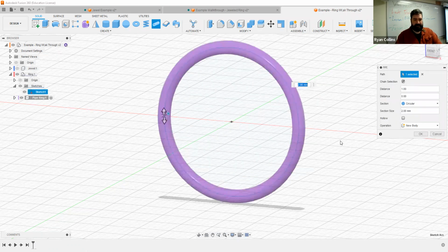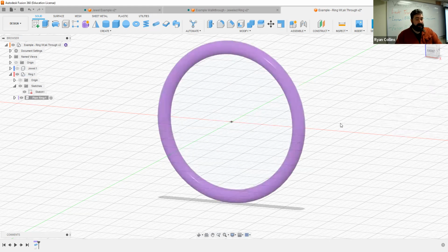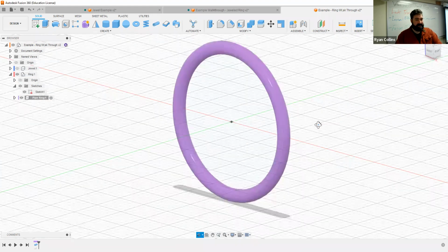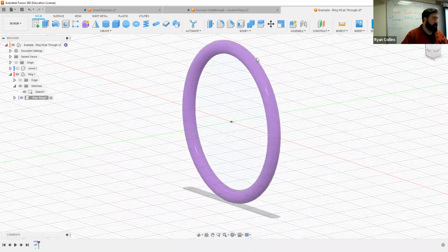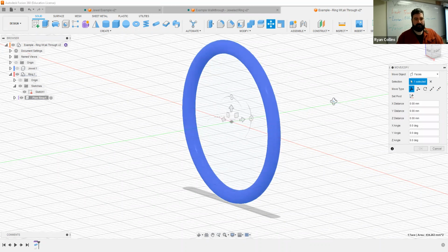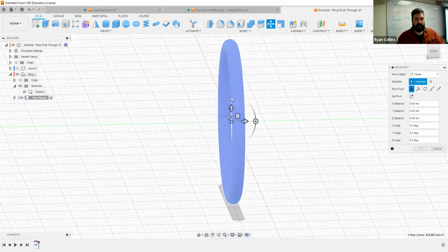All right. Inside of that, let's make a pipe. Select that center one. 2 millimeters. Great. Now, like I said, you cannot leave this as a simple direct pipe tool. What you can do, though, is you can make multiples. So let's take that direct pipe tool and let's move this, press M, and I'm going to rotate it across the x-axis.